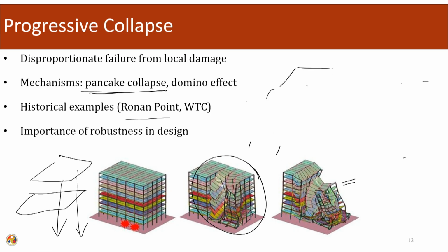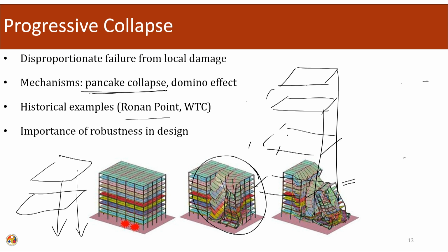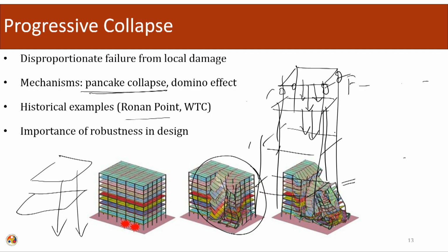So, what happened was that each of the slab systems was joined by a framing action. Due to the excessive heat, the connections were no longer able to take the load. So, they became overstressed, and one slab on top of the other slab kept on pounding. Due to the fire, the initial collapse started, and after that, due to the self weight and the pounding effect, the entire system collapsed like a pancake. So, this is one of the most well known collapses.